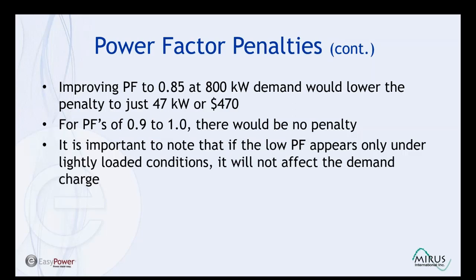It is important to note that if the low power factor appears only under lightly loaded conditions, it will not affect the demand charge. If our power factor penalties are only applied as an increase to the demand charge, then having a low power factor under lightly loaded conditions is not a problem.